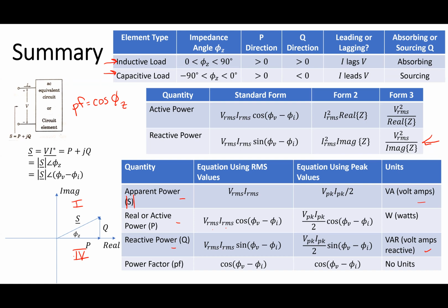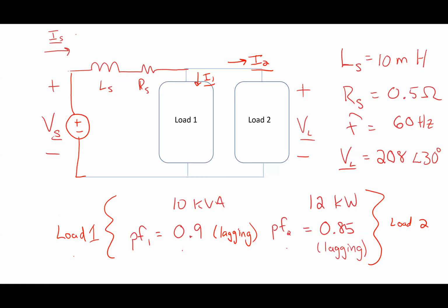Do you have a question there? I was going to say, is the power factor just P divided by S? Yes, because of the way this is set up, the power factor is always P divided by S, but I can't tell whether this angle is negative or positive. If the angle was 30 degrees, cosine of 30 and cosine of negative 30 is the same. From the information I gave you, you wouldn't have enough unless I tell you that it's lagging. So when I told you it's lagging, what does that mean? It tells you the angle is positive.